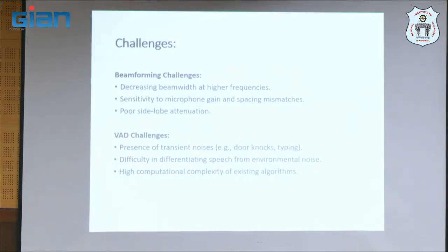Among the challenges we are going to face in beamforming and VAD: in beamforming, at higher frequencies the wavelength decreases, so the beam becomes narrower, so the beamwidth decreases, and side lobe attenuation becomes poor at higher frequencies.